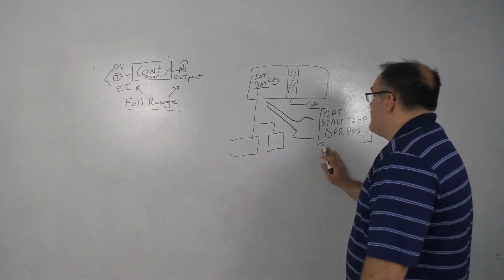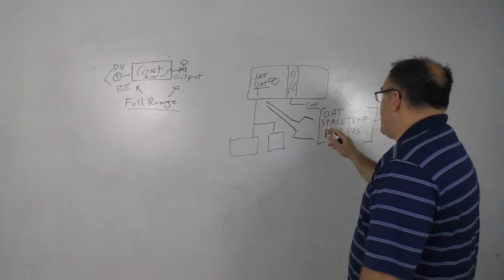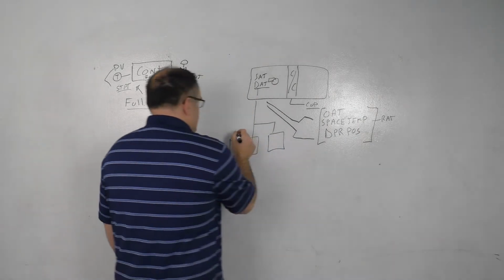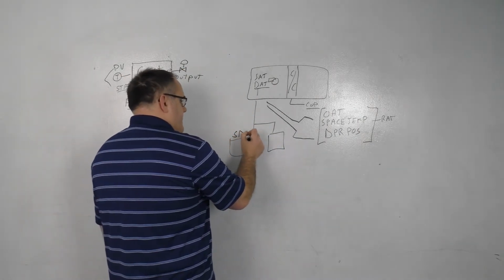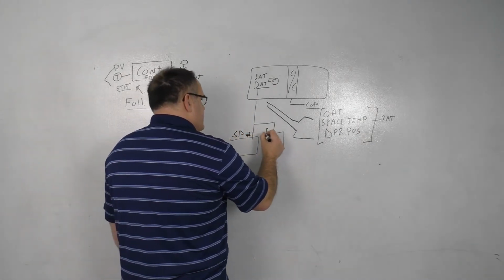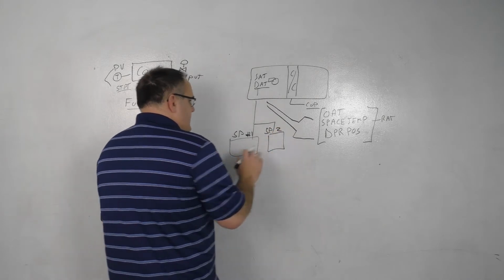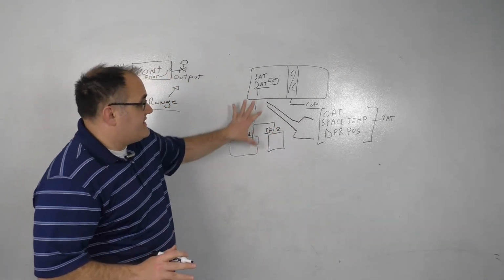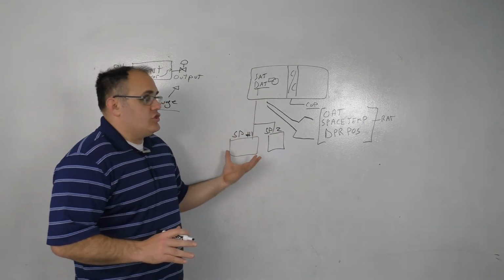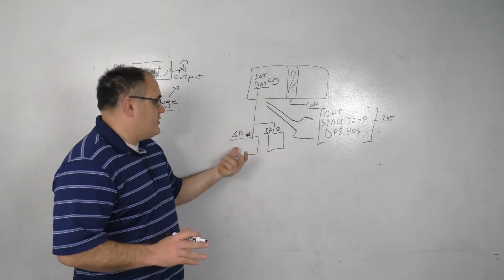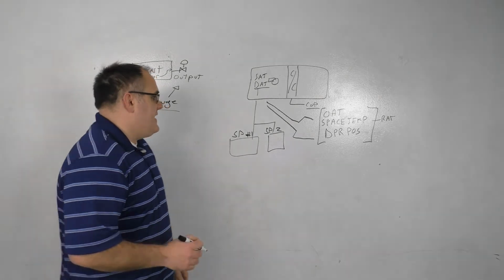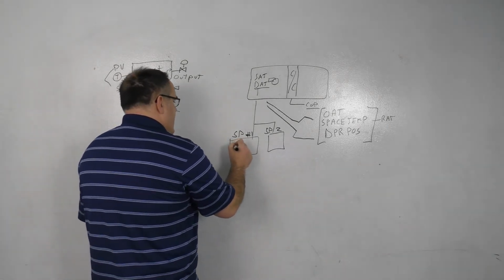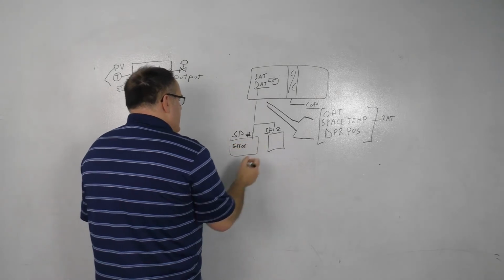After that, we've got outdoor air temp, and we've got space temp. In this case we've got space 1 and space 2. With space 1, if it's a single space, then we just look at the space temp and the difference between space temp and set point. That difference between space temp and set point is error.